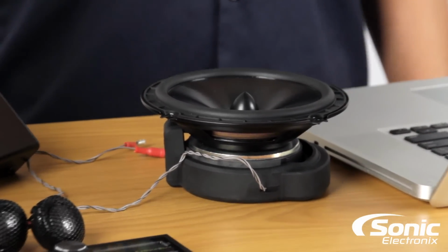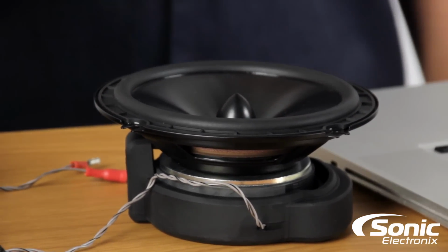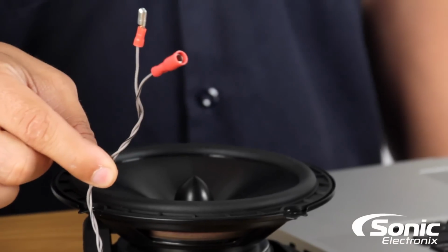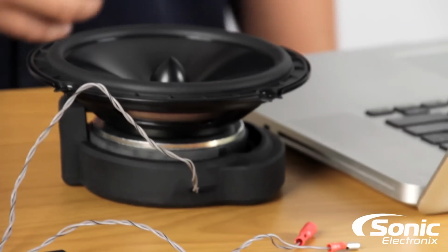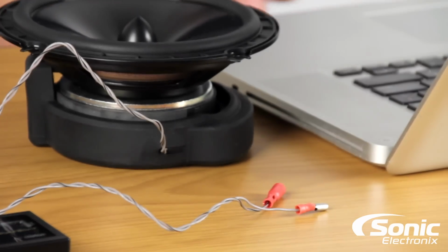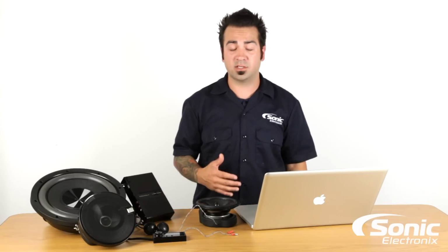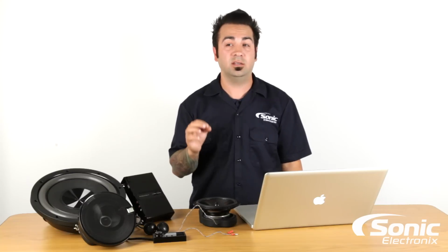So earlier, Mike had said that the power and signal get sent through two wires. This is all that comes off the back of the speaker, as you can see here. Just two very thin wires, which is really neat. So you're not running power to your amplifier, you're not running remote. This is totally different. Obviously pretty much all conventional amplifiers are going to need power, ground, remote, RCA signal, and of course they have your outputs. Clearly you can see this operates completely differently.